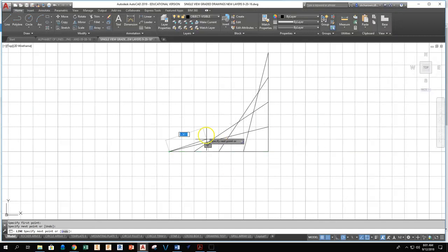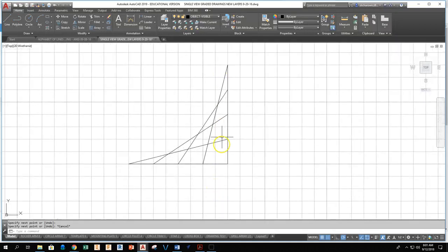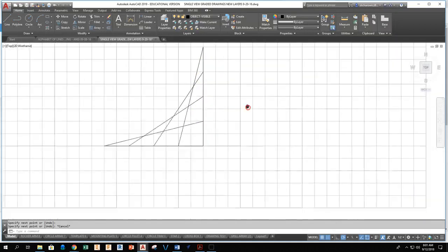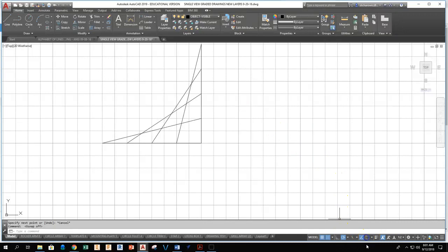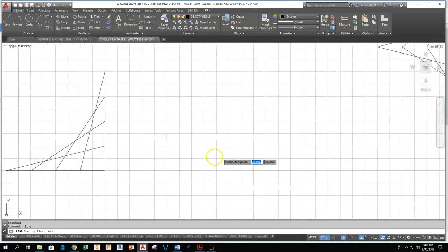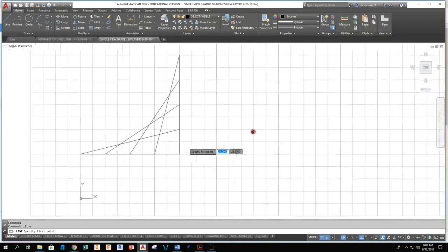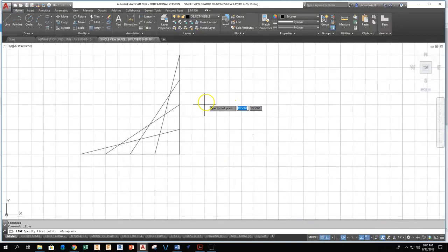So that is one way that you can adjust and manipulate using snap versus OSnap. The other thing you can do is turn off your OSnaps, and then no OSnap will be functioning, and you will not need to sit and hover to override the OSnap. It's just another way that AutoCAD can function, in that you can turn things on and off. I highly recommend, if you turn off the OSnap, make sure you turn it back on when you draw anything else. If you don't have snaps, you need OSnap. If you don't have your OSnap, you need your snaps. And you must then make sure everything is based off of 0.5.